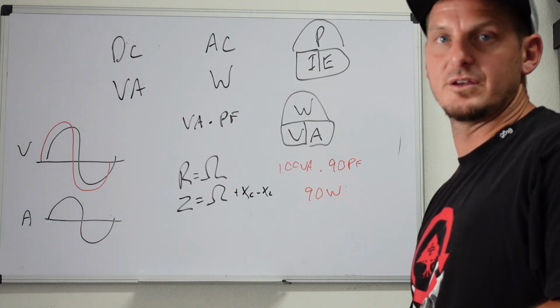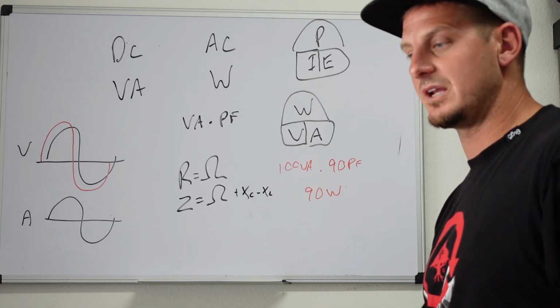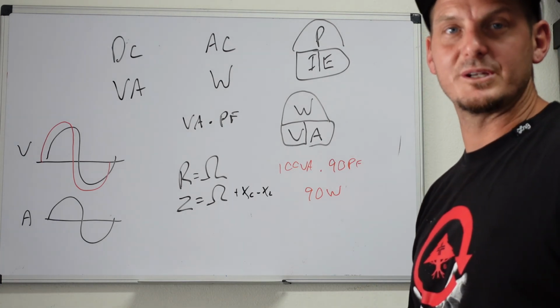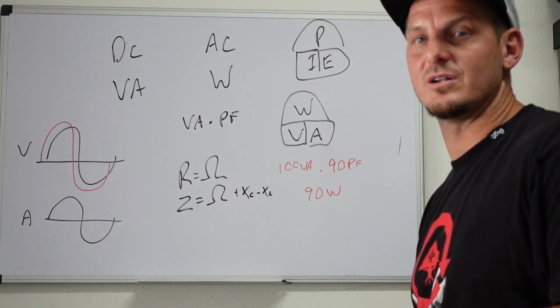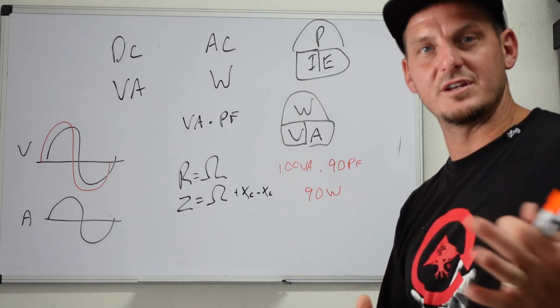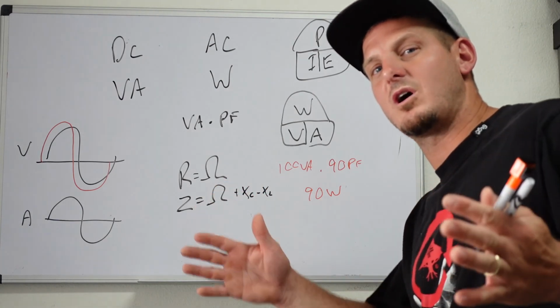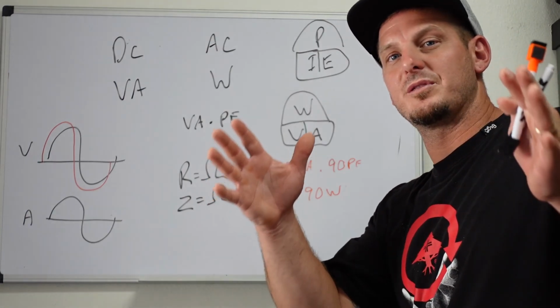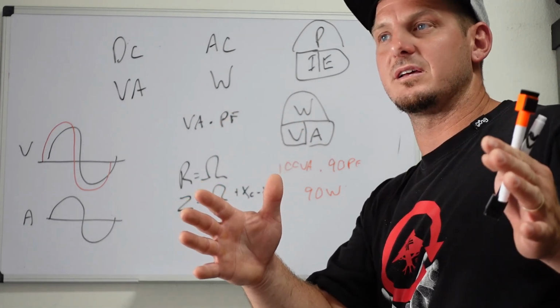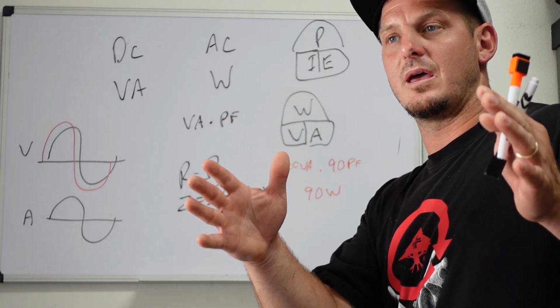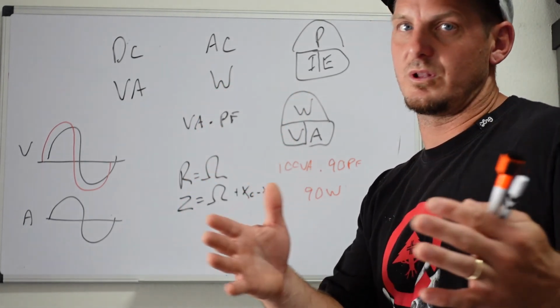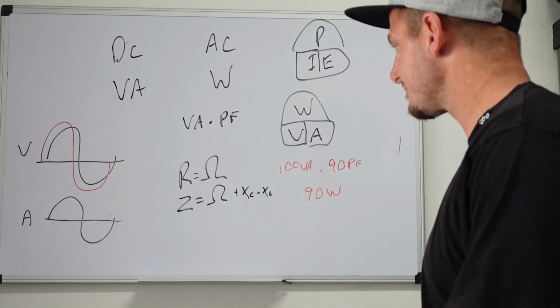They promise to deliver you at a certain percentage, and your meter will actually read power factor as well, because it's able to tell how much VA it's sending, and it's able to tell how much wattage you use. So if it's not within their guidelines of what they're providing and what they say they'll cover, you will actually pay more for that power.